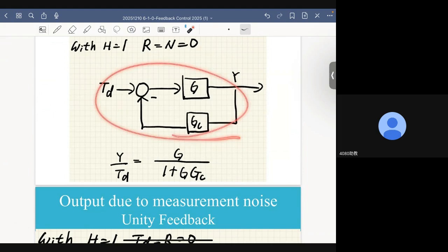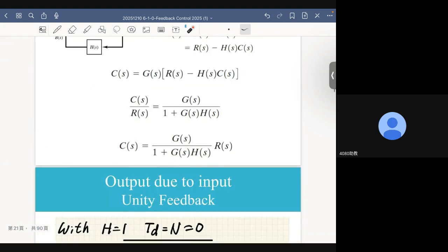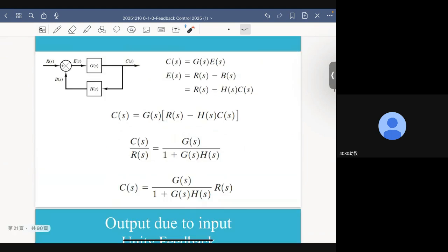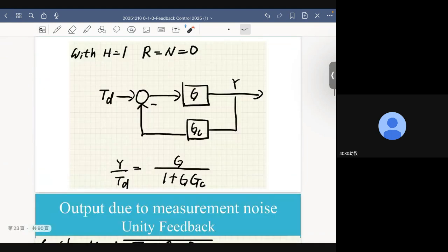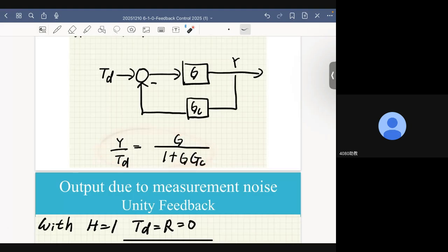Now, for this feedback control system, by using, again, this equation, which is the result of this block diagram, we can determine the transfer function between input disturbance and output. That is a very systematical approach to help us understand the impact of the input on the output, all right? Because we know their interaction by establishing the transfer function between them, all right?